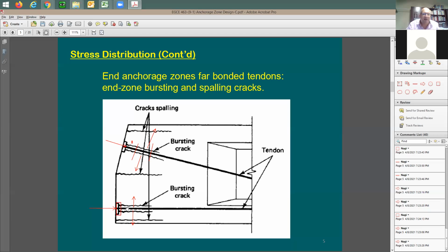And this is going to be part of the loss that happens to your pre-stressing force. Once you start to move this block inside, the extension that you provided to the strand, you're going to be losing some of it. And you don't want this to happen. So this area of the beam needs to be very rigid, and you cannot allow any movement of the end block or the bearing plate. Otherwise, you're going to have more losses.